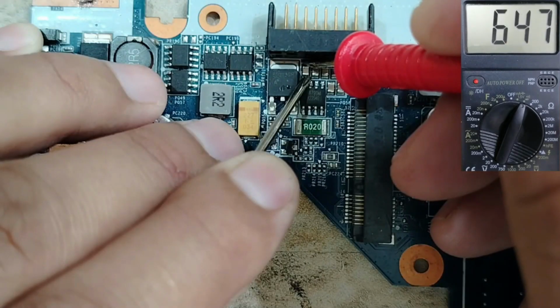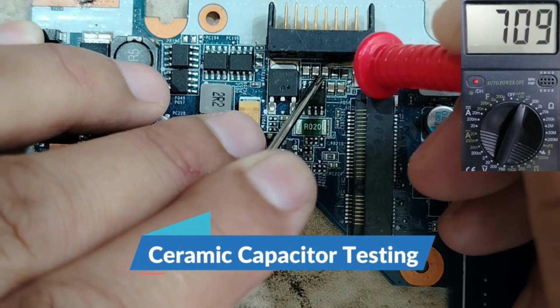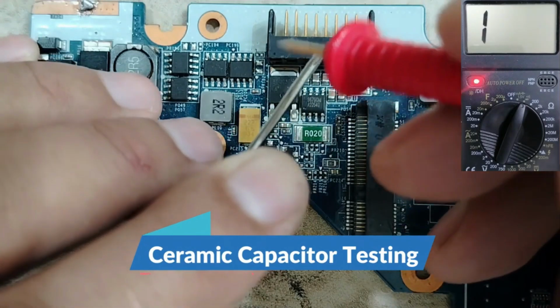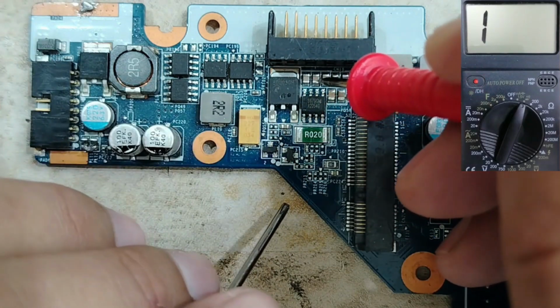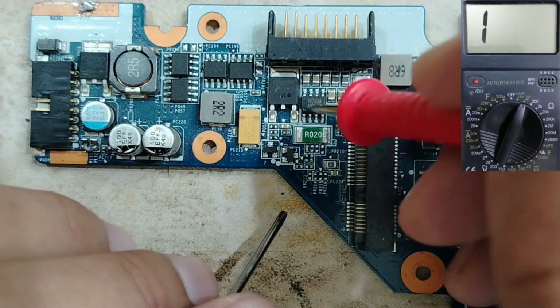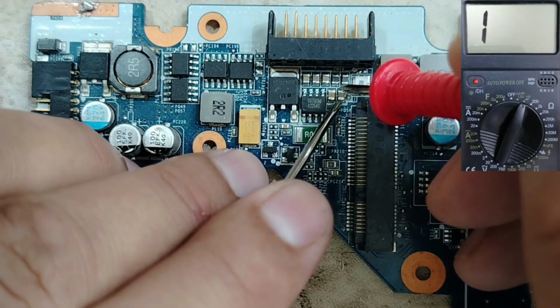For a ceramic capacitor, we should get a high reading, as you can see in the multimeter. If you get a short or a low reading like this, it means the capacitor is shorted, or the IC near the capacitor is shorted. Let's check those also. Good.